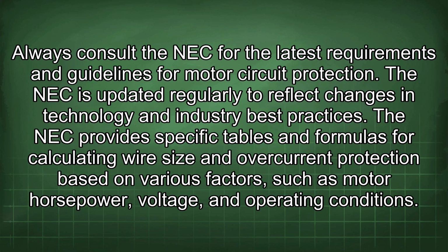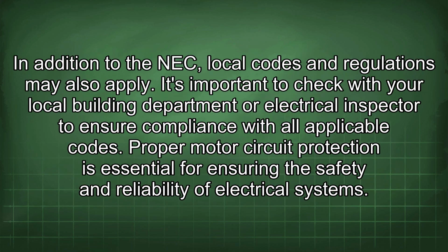The NEC provides specific tables and formulas for calculating wire size and overcurrent protection based on various factors such as motor horsepower, voltage, and operating conditions. In addition to the NEC, local codes and regulations may also apply. It's important to check with your local building department or electrical inspector to ensure compliance with all applicable codes.